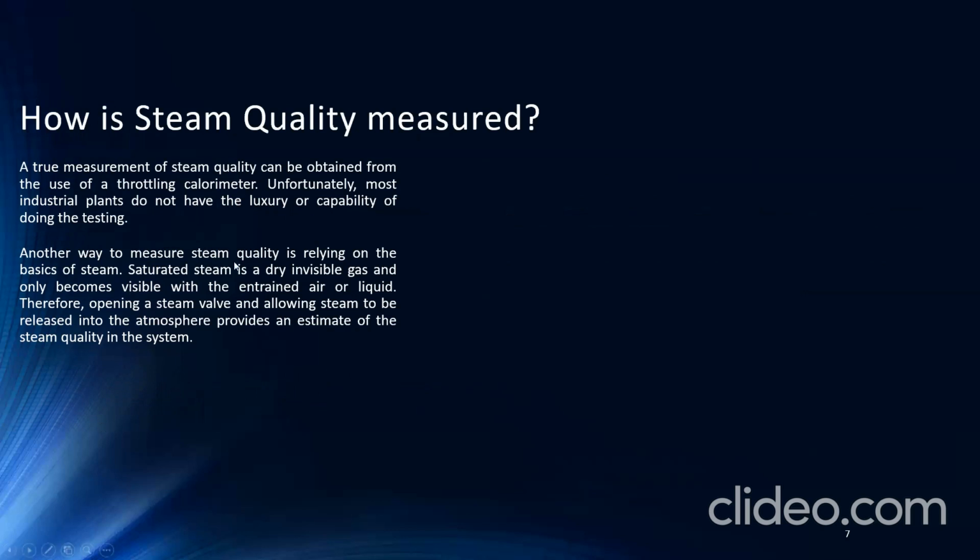Another way to measure steam quality is relying on the basics of steam. Saturated steam is a dry, invisible gas and only becomes visible when the entrained air or liquid condenses. Therefore, opening a steam valve and allowing steam to be released into the atmosphere provides an estimate of the steam quality in the system. When you release it, like the figure earlier, they just released the trap.